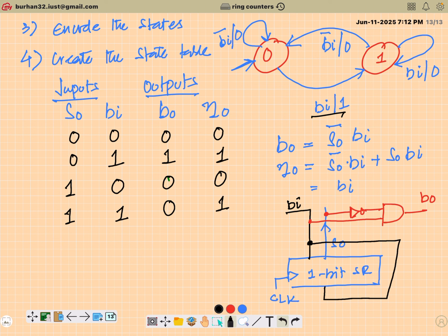Like I said, it is slightly difficult to capture Mealy machines, but once you capture it, it actually allows you to capture the behavior in a lesser number of states, generally speaking. And a lesser number of states, when translated into hardware, will result in lesser hardware. We'll do some more examples in coming videos about this Moore and Mealy machine. Stop here.